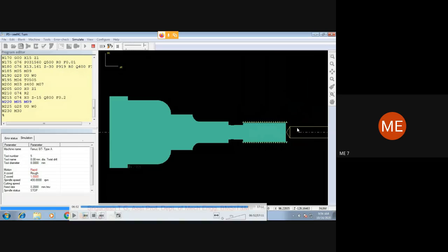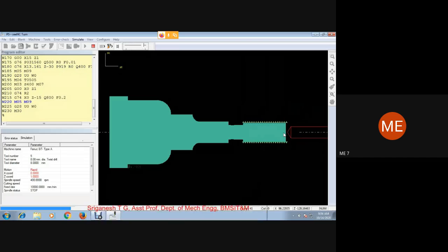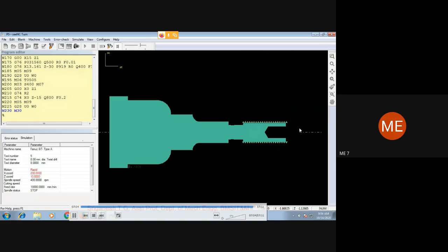Yes, and then comes the drilling tool. So first it has to be here. There's a gap between the workpiece and the drilling tool, okay, and then it is going to do its operation. Right? So it's going to retract by 2 mm every time after every 800 microns of drilling. Yes, so this is the simulation.